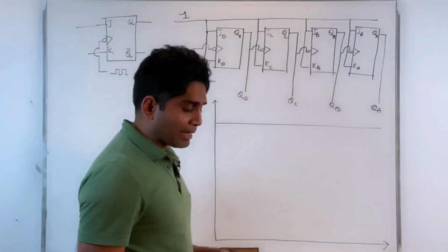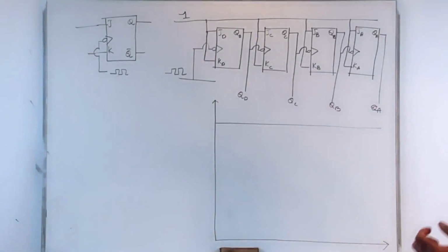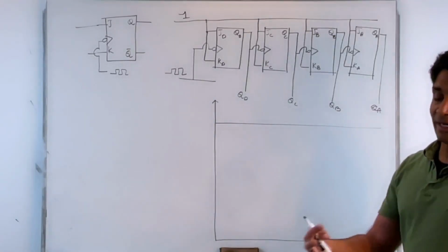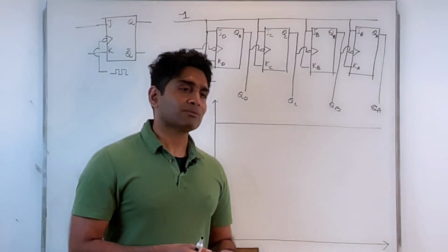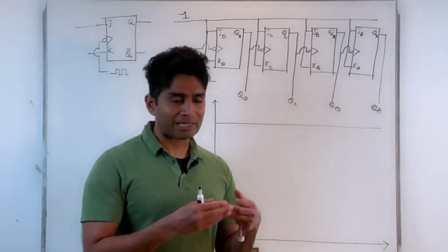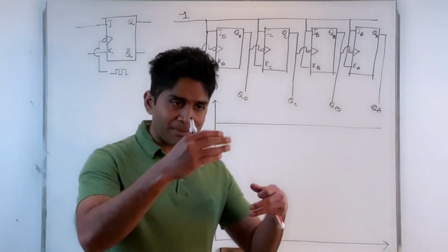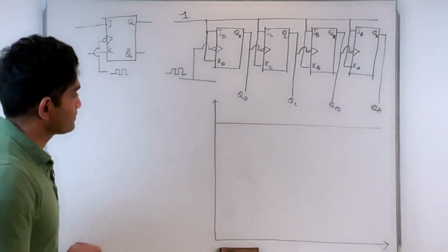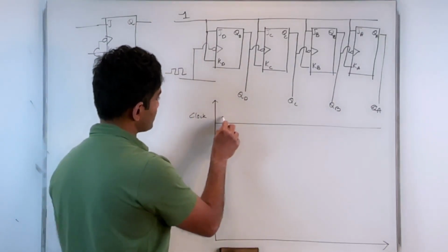Again, whenever I'm drawing the timing diagram, I start with the clock because the clock is the one that's providing the timing information in the first case, and I want to reference everything, the timing information about the rest of the circuits, against the master clock. So that should be the practice. Okay, so that's your clock.